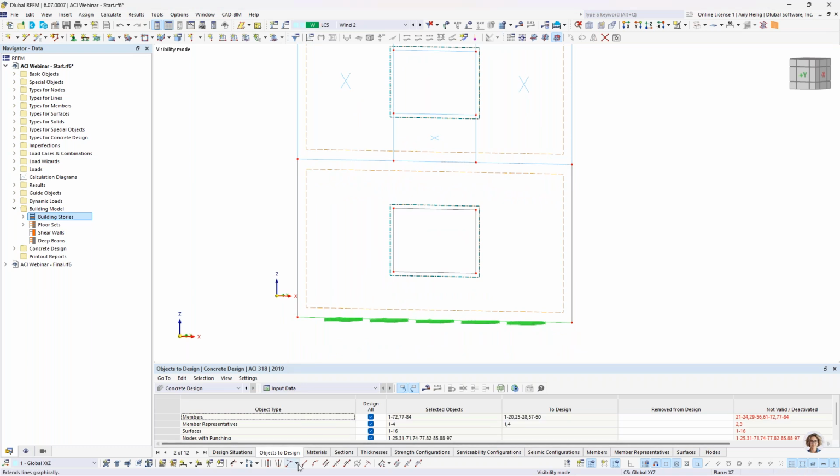It's in the program. With our drawing tools down at the bottom, we have this option to extend the line graphically. So something that you might find similar in AutoCAD. When I choose this option and I hold down the Alt key on my keyboard, what will happen here is that the program will automatically extend this line when I click on it, the upper left and right hand sides, without affecting the opening.